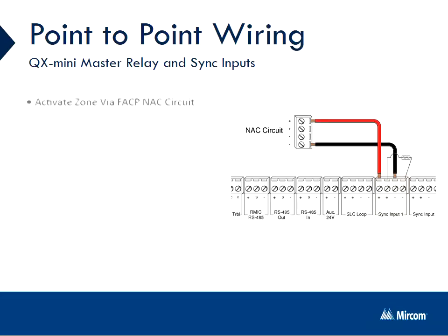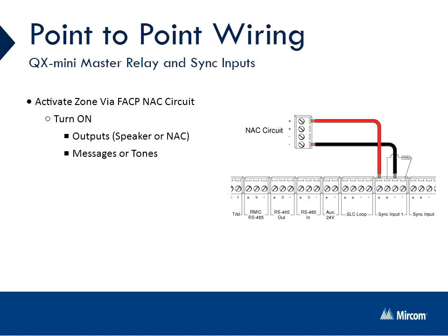Once the fire alarm is put into alarm, the NAC circuit on the fire alarm switches polarity and activates the sync input on the QX Mini panel, which can be programmed to turn on specific outputs and messages or tones.